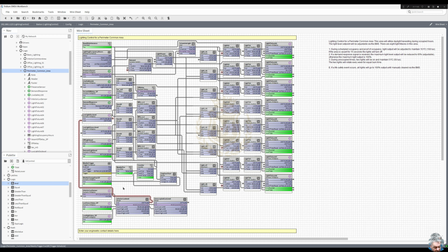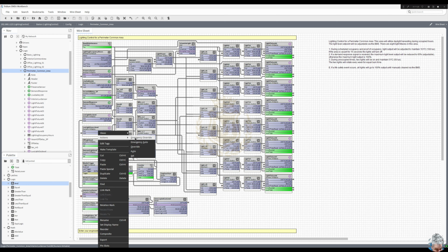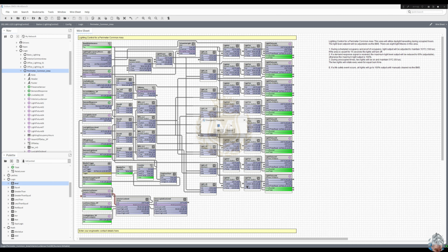But what we've got to do, and that's adjusted via this sensor here, so the lux high value set point is 100. So once we go over 100, so the input low is 50 and 100, once we go over 100, it's going to be 0. But while we're in between, actions, emergency override, and we have a lux level of 60, we're giving 80%.